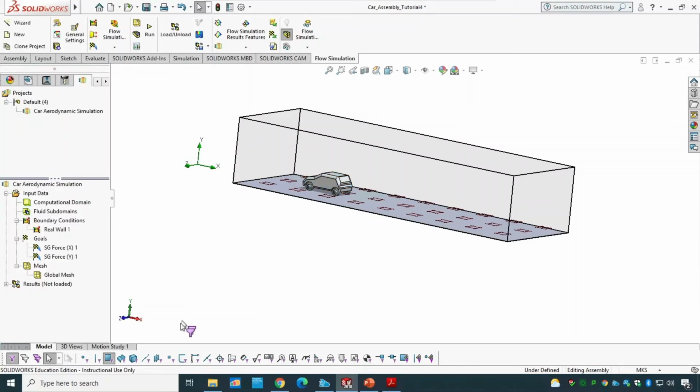So something was important. I used the filters to be able to do it. So what you will see then, we have the force X, we have the force Y in here, and we already applied the mesh, we modified the mesh as well. And so basically, let me go back with the no filter. I don't need any filter in here. I'm happy with everything. So I'm gonna just run the simulation, click on the run.